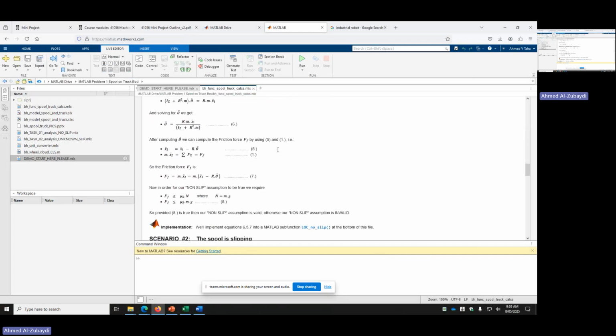And just remember something, if you get it wrong. Wait a second, let's talk about getting it wrong. That's something we also talked about last day with Brown. Many of the subjects in universities nowadays, not just ours, ignore this part. Now everybody accepts that the code you have is going to be correct and keeps using it to get results. Now the question is, if I make a model for a heat exchanger in MATLAB, how should I know that the calculations are correct? I should have an experimental work with the same conditions and verify the results against each other.